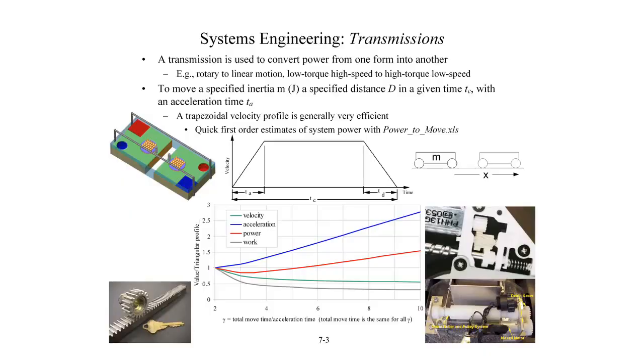Very, very critical. Now, between your motor, your power supply, and the thing that's going to move, you almost always will have a transmission. And the reasoning for that is it's really inexpensive to make a motor go really fast. But you often need lower speed, higher torque. So for example,